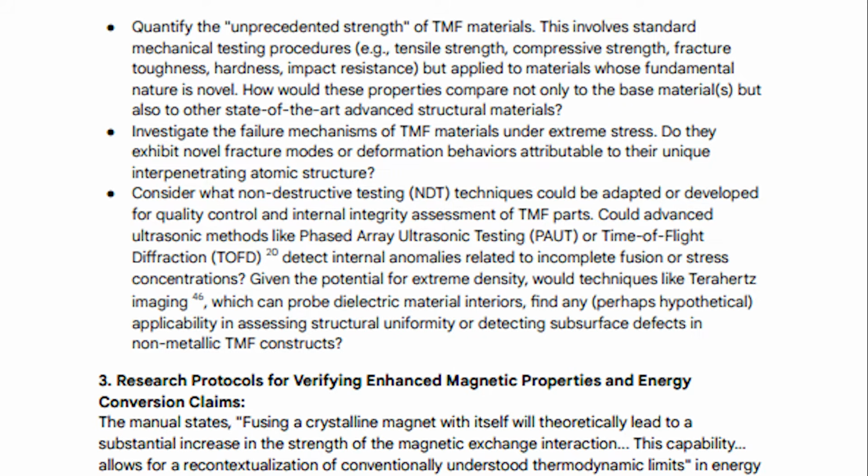Consider what non destructive testing (NDT) techniques could be adapted or developed for quality control and internal integrity assessment of TMF parts. Advanced ultrasonic methods like phased array ultrasonic testing (PAUT) or time of flight diffraction (TOFD) detect internal anomalies related to incomplete fusion or stress concentrations. Given the potential for extreme density, with techniques like terahertz imaging, which can probe dielectric material interiors, find any, perhaps hypothetical, applicability in assessing structural uniformity or detecting subsurface defects in non-metallic TMF constructs.